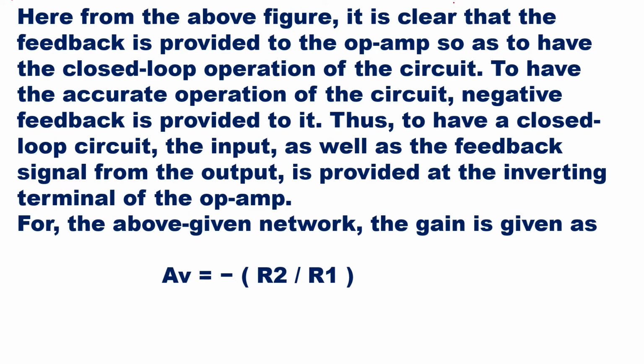In that way, you can choose the gain, you can adjust the gain, you can decide the gain in a closed loop circuit. And this gain was for your inverting amplifier. And minus R2 by R1, because the minus sign will come because you are having a 180-degree phase shift at the output. So here, this is the concept of inverting amplifier. Clear? Now we'll go next to see what is non-inverting amplifier.